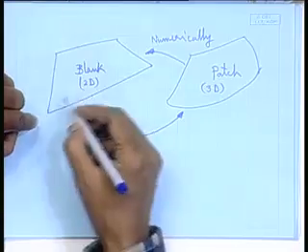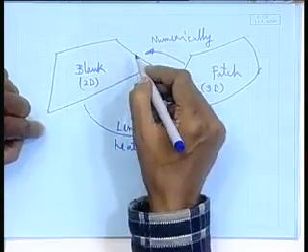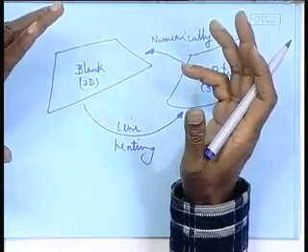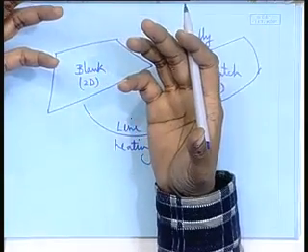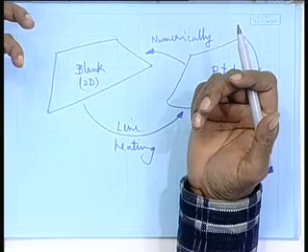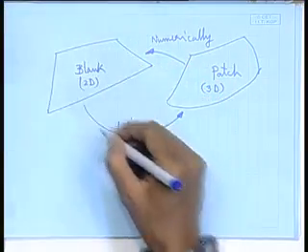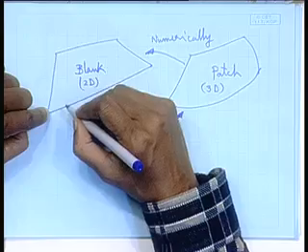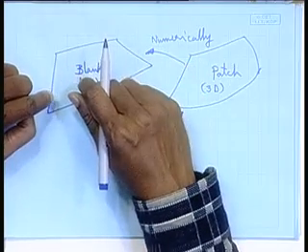So to get to this patch, I have to find out this heating pattern. Once I know the heating pattern, I apply it. There can be 10 lines of heating or 40 lines of heating depending on the shape. So these lines can be curves also? It can be anything, but generally we try to keep to straight line heating, wherever we can.